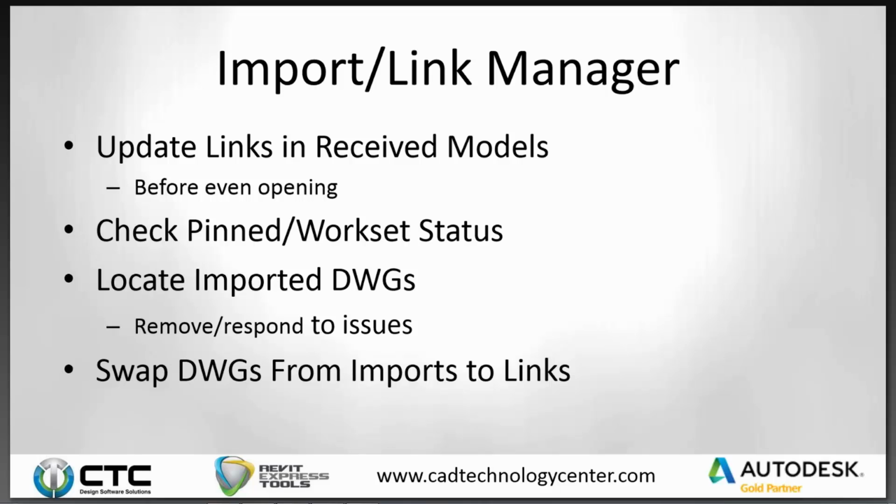And that has ballooned file sizes in a lot of cases. Revit does not like imported DWGs in a production model. Now, importing DWGs has its place, don't get me wrong. It's a good feature, especially when I'm managing details and trying to build up a detail container file. But live in my production model, I'm not a big fan of imported DWGs. I'd much rather them be links.